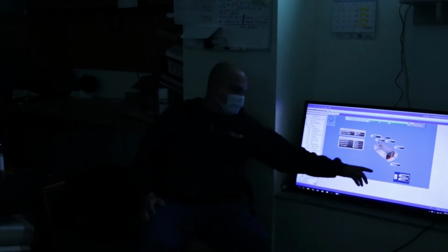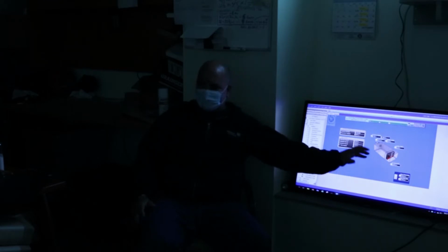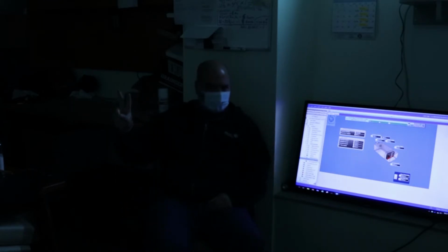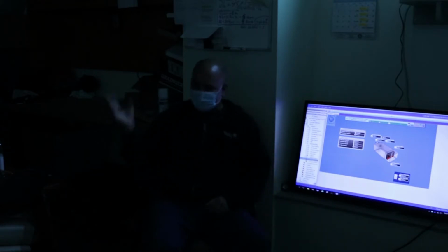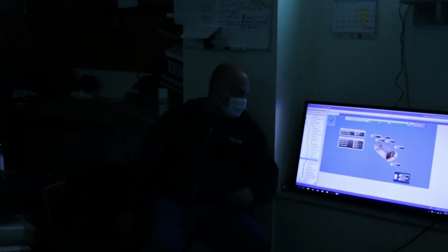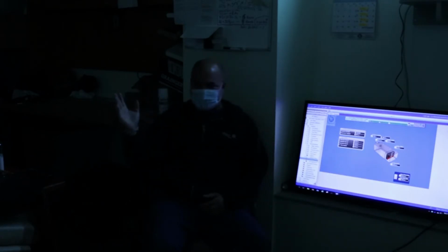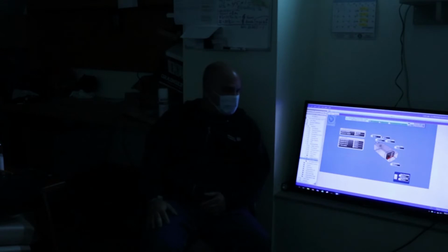Now, just to remind you that there's a 2-degree dead band in the thermostat. So just because you're at 73 doesn't mean you're in full cooling yet, okay? If you're 2 degrees or more away from it, then you're gonna be there. 2-degree dead band in the thermostats. So if you're at 71 and you don't see the heating valve start to open up yet, don't panic. You're starting to go in a direction, but you're not there yet.